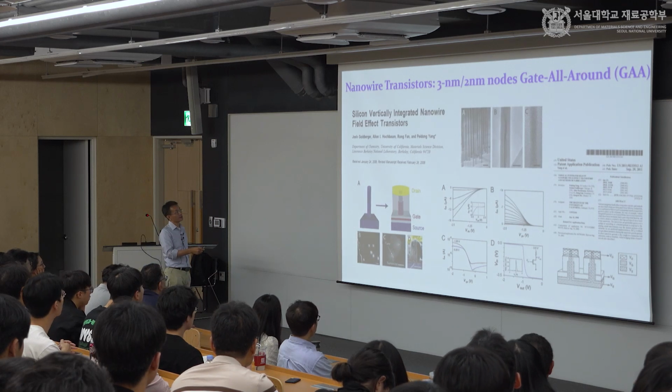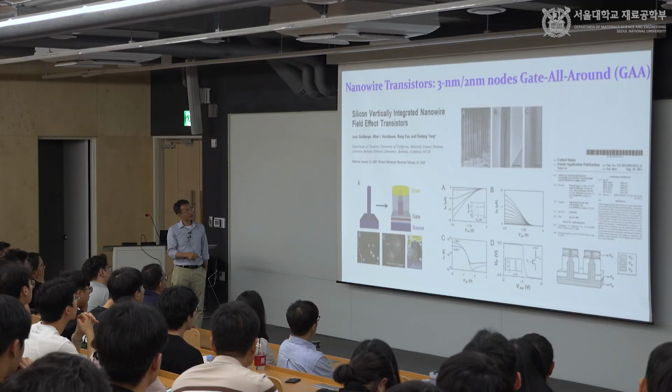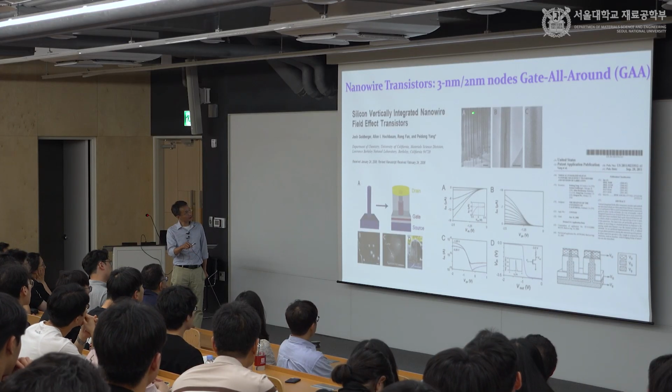As you can see, the advantage of the approach that my lab has been pushing is epitaxial growth of nanowires, vertically oriented. This gives us the opportunity to do this new architecture, which at the time we called surrounding gate. We can make these nanowires the active channel, make a vertical transistor, but more importantly, now the dielectric and the gate surround the wire.